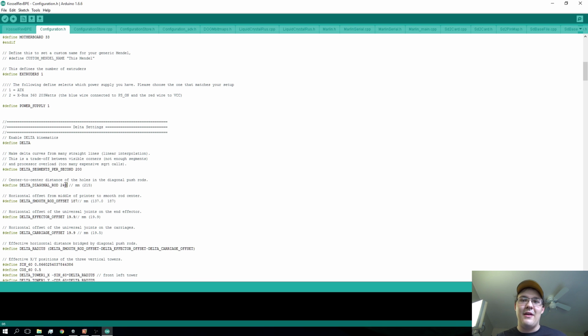Like I said, if the sizing is not correct, then adjust the 240 a little bit, like one up or one lower, and see what it does. Keep test printing until you get things where you want them to be. That's pretty much all you can do. When it starts to print, things should just work, as long as you have all your temperatures up to where they should be and have the settings right. Again, 3D printing, especially this kind of RepRap printing, is one of those things where you just have to keep using trial and error.